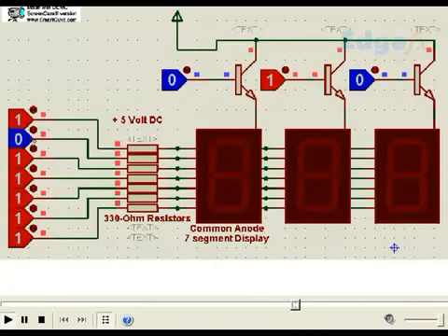These two are made low. When data for 7 is required, these 3 are made low. And that is how, when the data for 7, 1, 8 is coming, it is coming in this fashion from the data pins, and at that time the corresponding transistor is switched on.